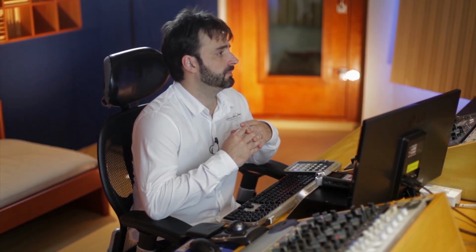Tom Hidley at the time designed control rooms with certain acoustic features that are still used today. The monitors were embedded in the front wall, like flush mount speakers. The ceiling and the back of the room should not cause reflections, no first reflections, just like recommended today. Hidley's project already had high symmetry between the left and right sides, and the reverberation time was low also in the low frequency due to the high absorption in this frequency range.